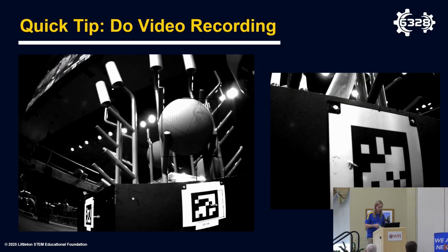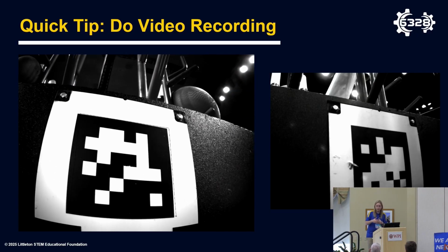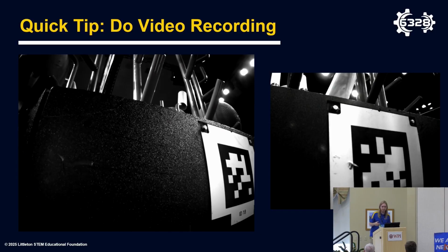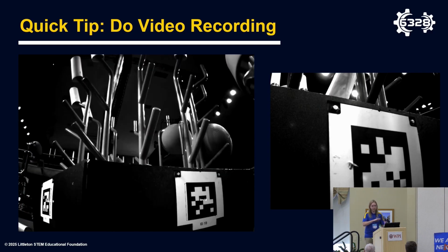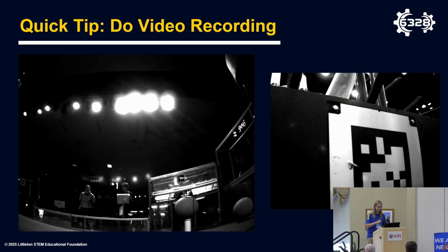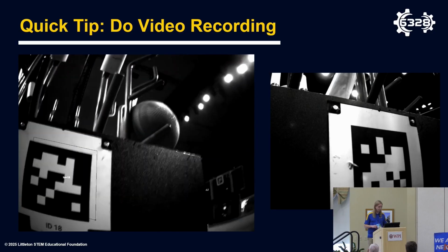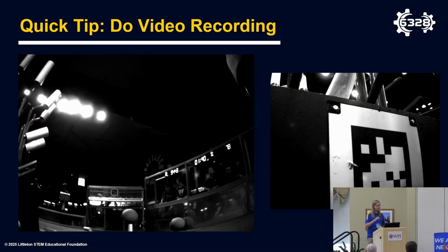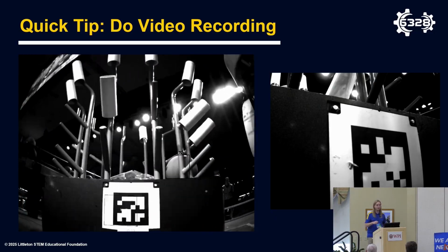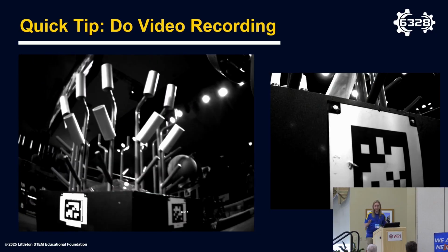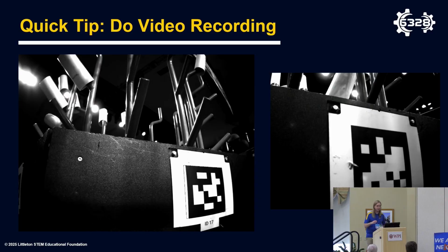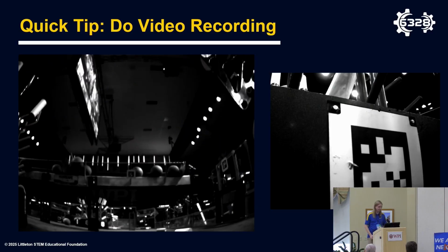This is something that we were testing out this year. Fundamentally, this really just allows you to solve a whole class of problems much more easily. If you have a failed April tag detection, you can just look at the video and see, was that because of a shadow or poorly calibrated exposure or a damaged April tag? You can see on the right there, this is real footage from our robot at Champs where we found an April tag that had this gash in the side that we couldn't detect. So we were able to work that out within 5 minutes of getting back to the pit and get the FTA to fix that. So we avoided the massive headache of trying to track down gremlins in our vision system.